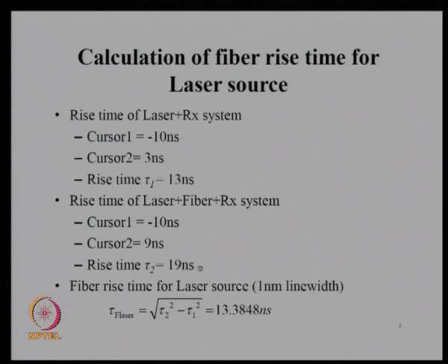Now this total 19 nanoseconds has the effect of the rise time for laser and receiver system as well. So to calculate the rise time of only the fiber for laser source, we subtract it from the total rise time. So we get the fiber rise time for laser source as 13.384 nanoseconds.